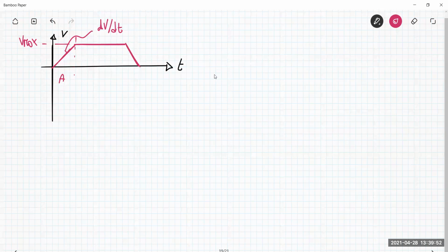The action of applying a positive voltage should be somewhat limited in order to avoid some mechanical failures inside the material. Because the material could break down, so it's no more useful. So when you want to get elongation, the acceleration of this movement should be limited. So I need this kind of slope.